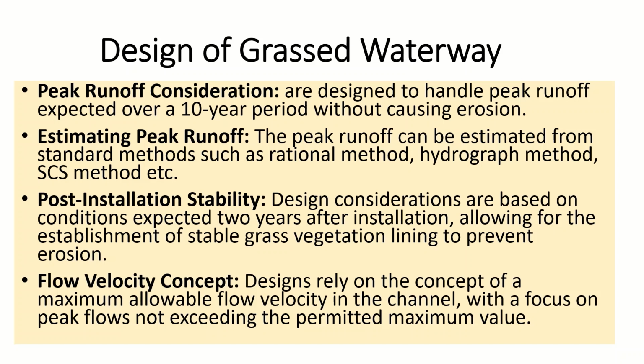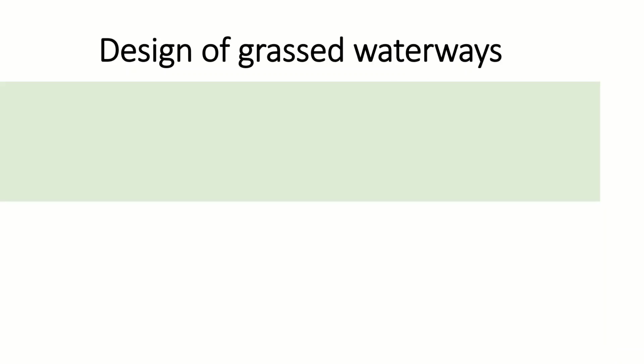So all these data are required. Some models you may have to use to estimate the runoff, and post installation stability is also considered in the design of a grassed waterway. So for designing a grassed waterway, usually a trial procedure is adopted.